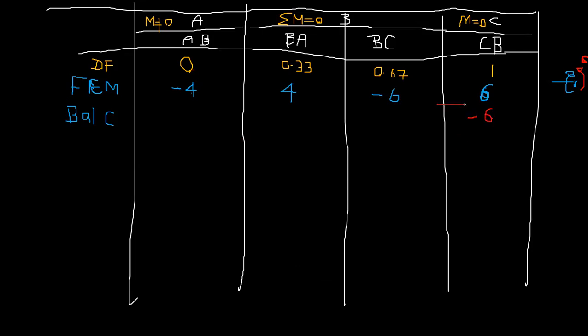Okay, so once you balance it, you consider carryover. What is the moment carryover due to the additional moment applied? That is the induced bending moment at the next end. Carrying over is done within the same beam, the same neighborhood, as we discussed earlier in the videos.